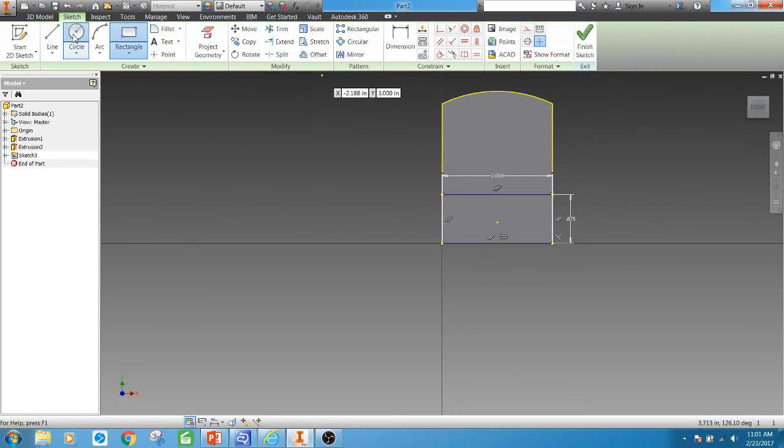The next thing we're going to do is put a circle right there in the center. And if you guys can see underneath my cursor, there's a dotted line that's grabbing the geometry of the center of your rectangle. So if you can grab it, you can go ahead and do that since it's supposed to be right there center anyways. The diameter of your circle is supposed to be 0.75 times 2.